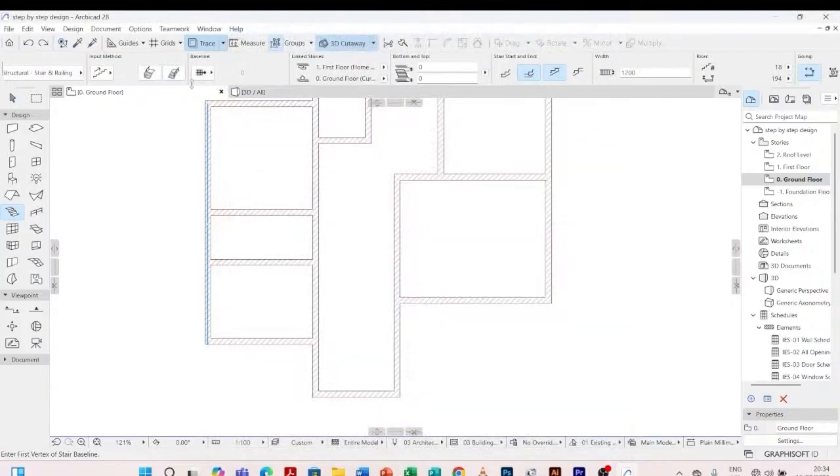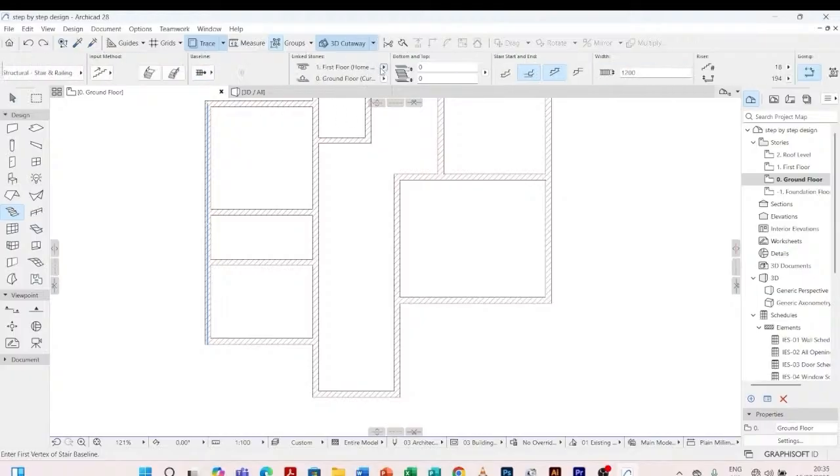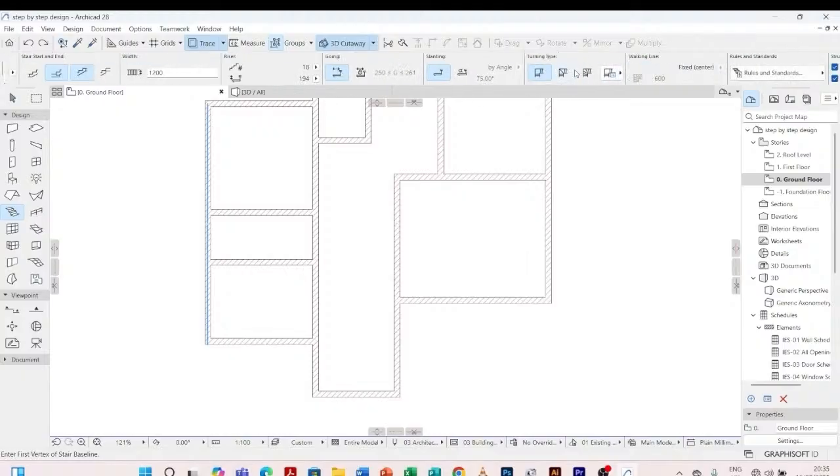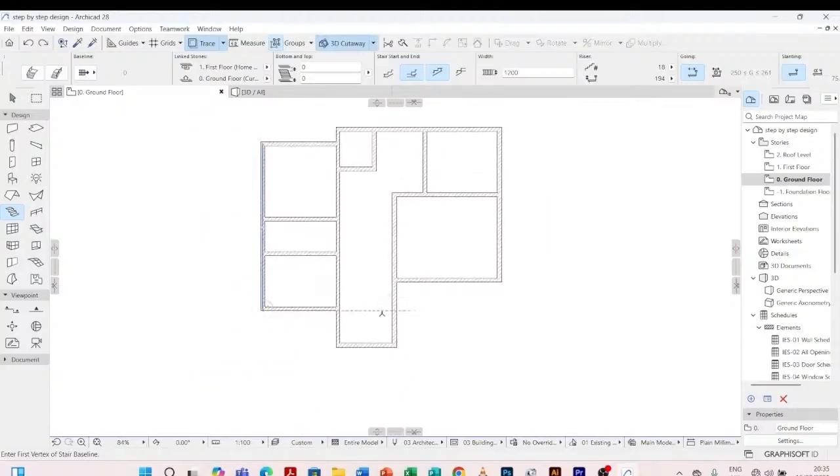Yeah, so then here, if you want it to have guardrails, you can place them on left or right. Then here, method of drawing it, constructing it. I prefer most times using center line. All these settings we have looked through them. So for this case we're selecting center line. Then these ones, they are 18. Yeah, so we can draw it. We can have our staircase drawn here.